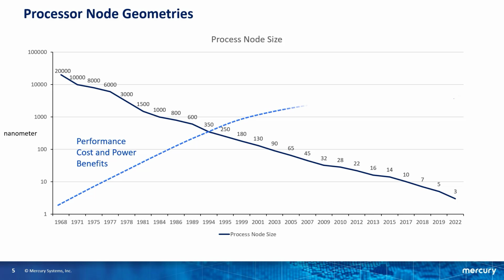As the nodes get smaller and approach the theoretical limit of 1 nanometer, a few things tend to happen. Transistors become more leaky, meaning that even in their off state, some current gets through, and that leakage current goes up as we get closer to the 1 nanometer, losing some of the power advantages we saw at the beginning of the curve. Also, with the extreme miniaturization, the resistance through the node increases. Coupled with the inherent capacitance of the node, switching speeds tend to slow down.